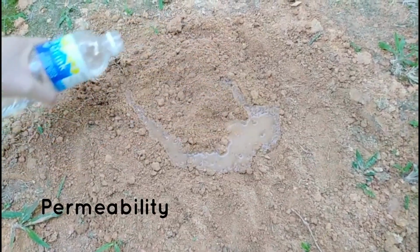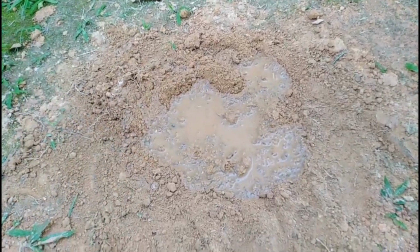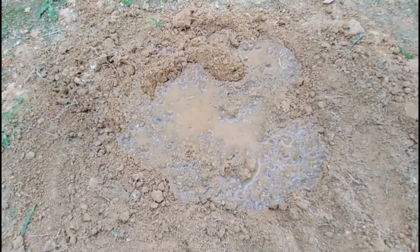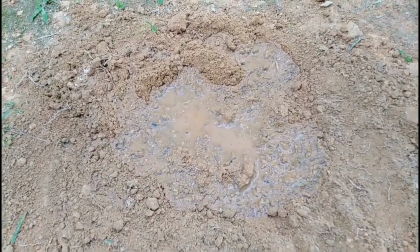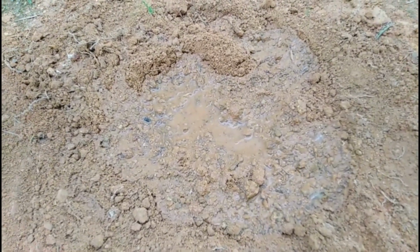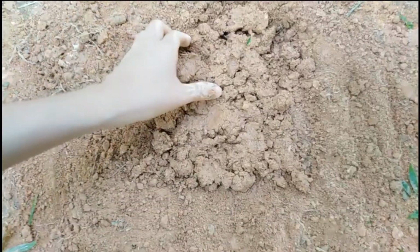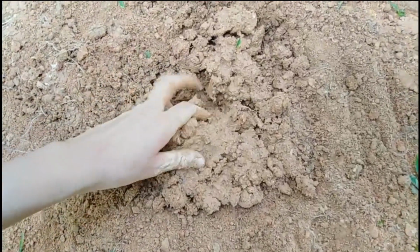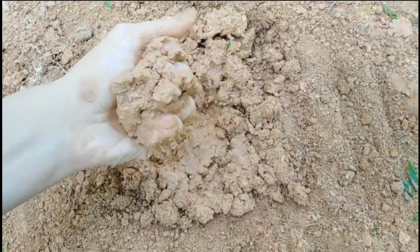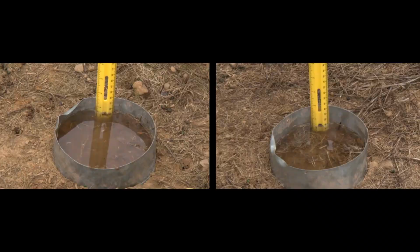Now I pour some water over them and see how well they drain. Since silt has a slightly larger particle size when compared with clay, it has a greater ability to drain, but it's still a poorly permeable soil type, which results in a medium infiltration rate and slightly poor drainage. As more water fills the pore space, the air is pushed out. When all pore space in the soil is filled with water, the soil becomes saturated.